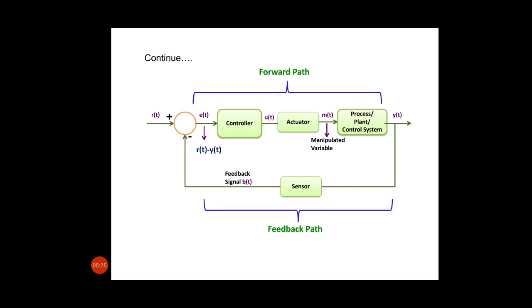In other words, if I use a sensor to measure the temperature at this instant of time, it may not show the temperature value instantaneously. The correct value at this instant of time may be shown after a certain response time, which needs to be characterized by what is called sensor dynamics.